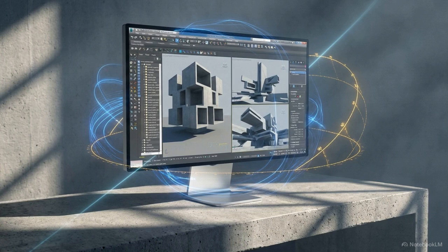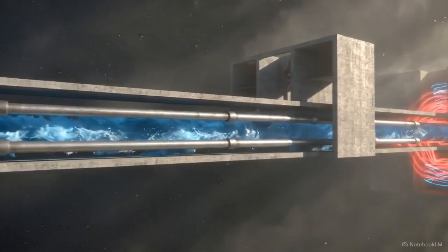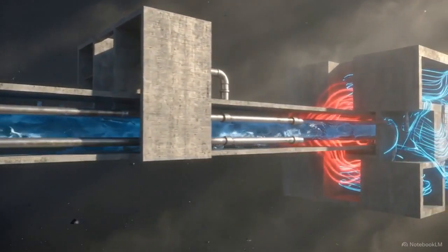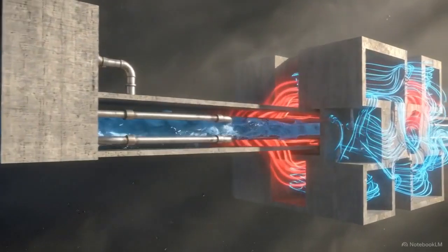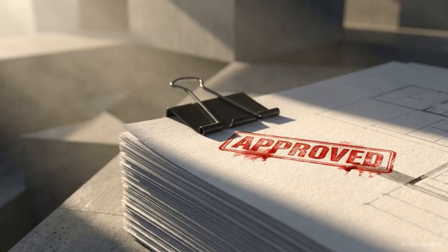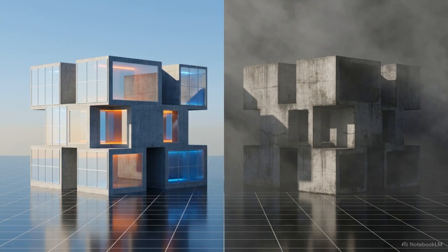The industry-standard computational engine responsible for calculating this EPI is EnergyPlus, which is frequently accessed through visual interfaces like Design Builder. EnergyPlus is chosen for its immense computational depth, executing simultaneous simulations of energy, water, and ventilation flows throughout every zone of a structure. Achieving a compliant EPI through this engine provides hard empirical proof that your architectural design actively conserves resources when compared to the absolute worst-case legal scenario.